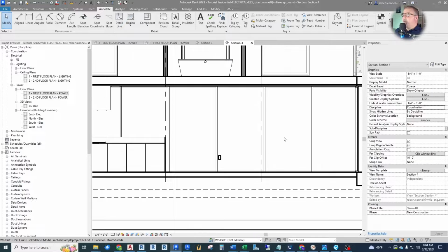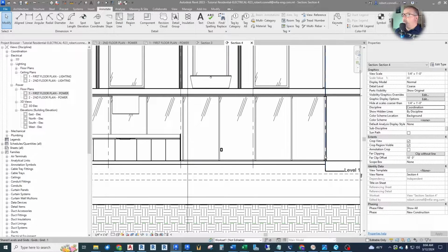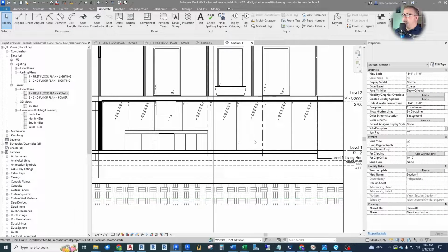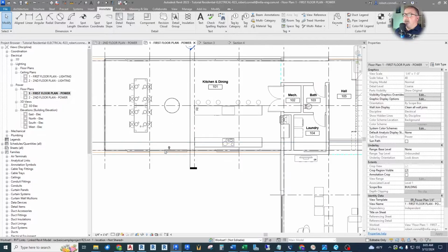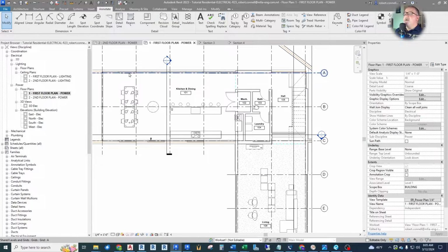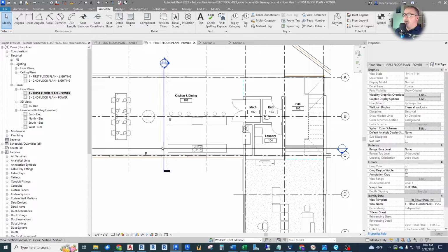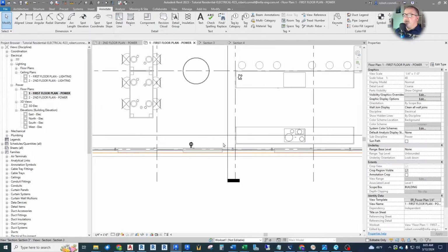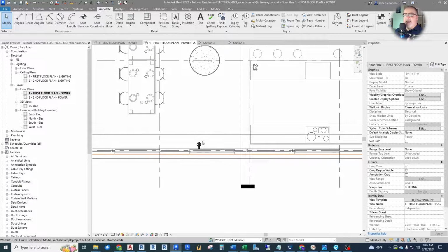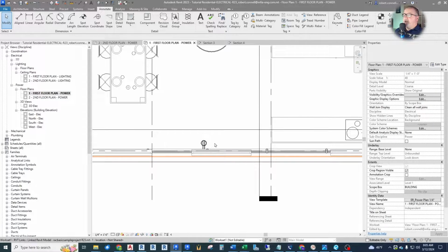So it looks to me like we have window, see the glazing, all the way to the floor along this. So that's going to be fun for our receptacles. That's what I was afraid of, that we have window all along this entire living space. Well, it looks like the owner of this building gets to invest in some floor outlets. The other thing you can do is hang an outlet from the ceiling on a cord, but I don't think that's going to be the preferred option here. So we are going to be getting into floor outlets.